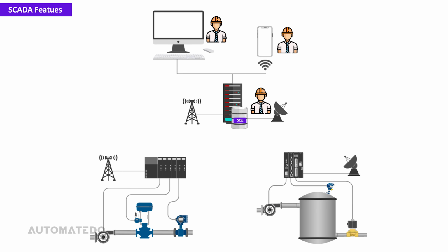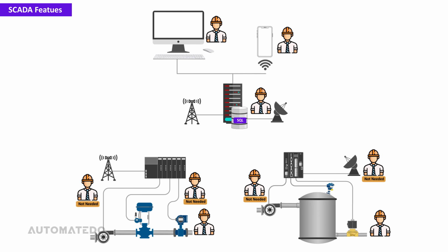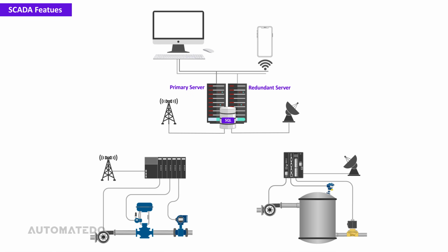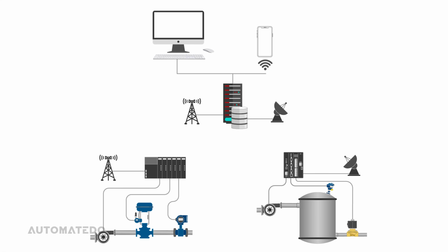You can manage to control complicated systems with well-trained personnel of the SCADA Control Center. This way, you don't need to have a vast army of specialists since the trained personnel can handle different situations with the help of leverages provided by the HMI software. And sometimes multiple servers are arranged in a dual redundant configuration to enhance the system integrity. This way, if the primary server faces any breakdown or fault, the redundant server takes over and ensures continuous management and monitoring.